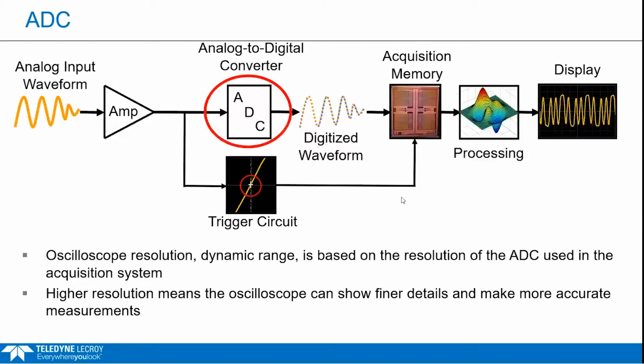Of course, there is our ADC, and all oscilloscopes have hardware ADCs. Many times they're supported with post-processing to get a higher effective number of bits, but we are basically going to use that ADC with the sample and hold, using the number of ADC bits and quantization levels to create and store all the voltage values and convert them to a number.